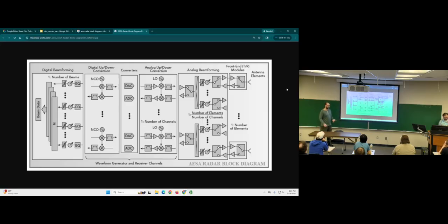They're almost always operating at S-band or X-band, aka 2 to 4 gigahertz or 8 to 12 gigahertz. That's very, very fast. Sampling that means double that frequency in terms of sampling. That exists, it can be done, but why, if you don't have to? And the answer is you use a down converter or an up converter.